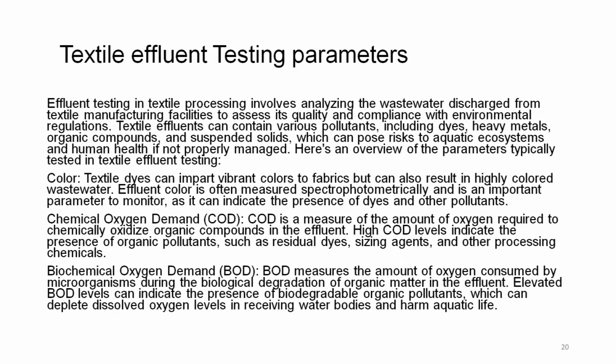COD is a measure of the amount of oxygen required to chemically oxidize organic compounds in the effluent. High COD levels indicate the presence of organic pollutants such as residual dyes, sizing agents and other processing chemicals. Biochemical oxygen demand, BOD. BOD measures the amount of oxygen consumed by microorganisms during the biological degradation of organic matter in the effluent.